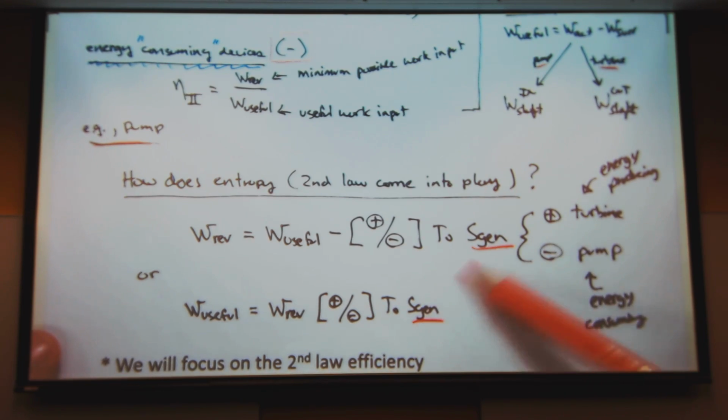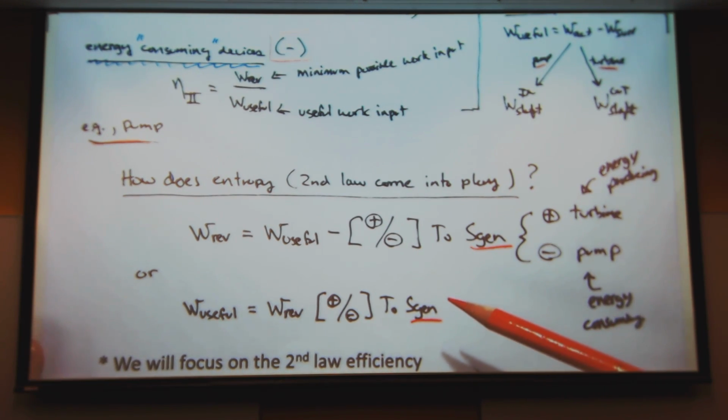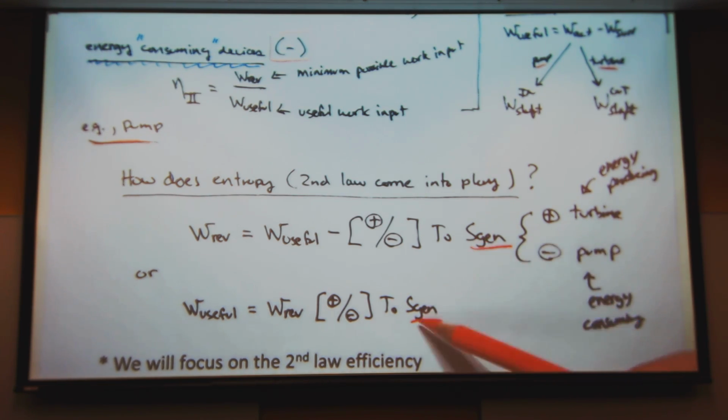Usually we have irreversible processes when we operate them and then try to operate them in the opposite direction. There's always going to be some area under the curve, or if we go through a cycle, there's always going to be some irreversible heat loss. In that case, there's going to be some entropy generated because of those irreversibilities during the process. Then we calculate those, and we can take into account the useful work relative to the maximum amount of reversible work.